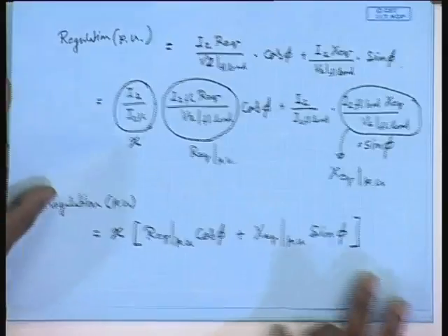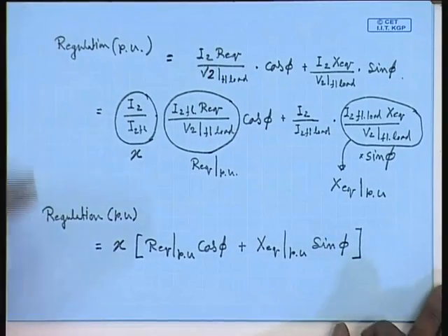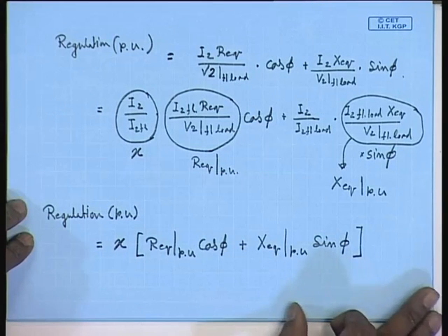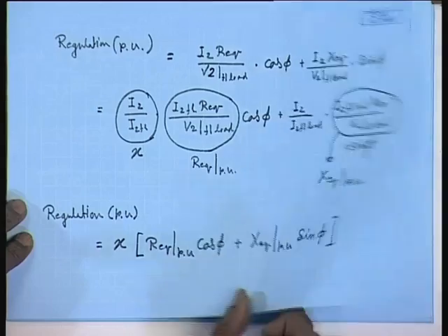Similarly, it will be interesting to find out at what load power factor angle the percentage regulation is maximum. This is obtained by differentiating the expression.